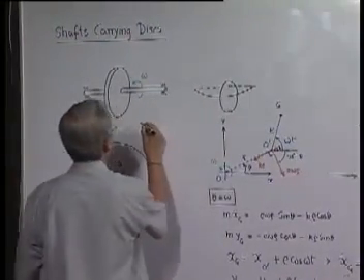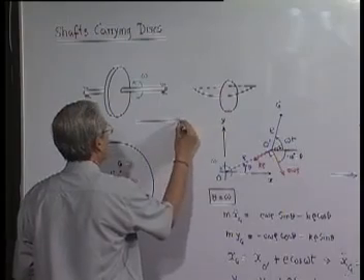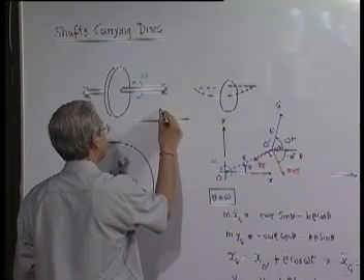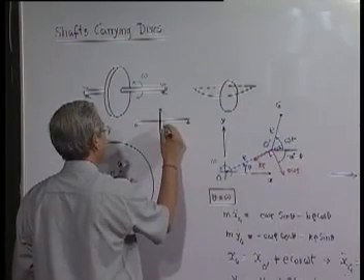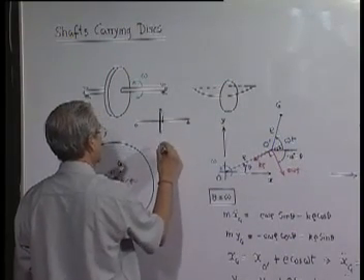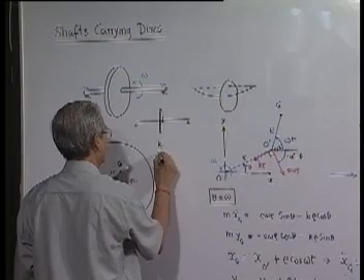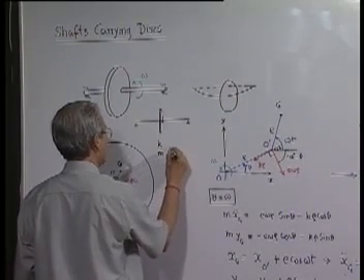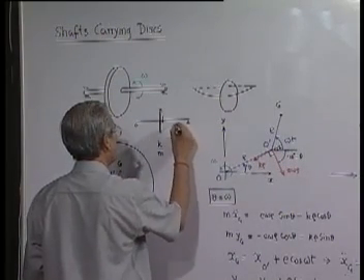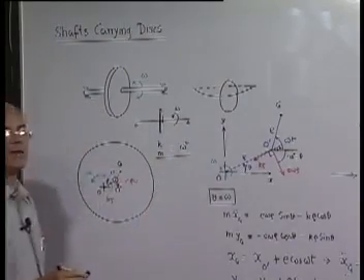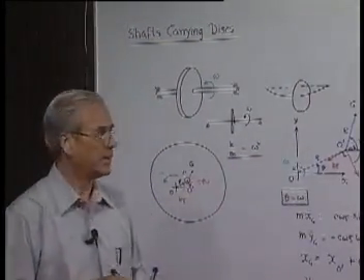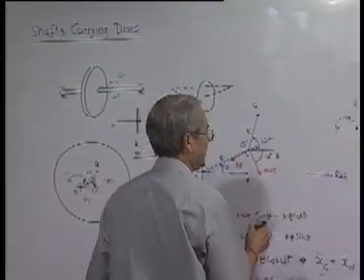If the shaft is like this, then the equivalent stiffness of the shaft here is K and the mass of the disc is m. If omega is the rotational speed of the shaft, then again something like resonance takes place. This phenomenon is called whirling of shaft.